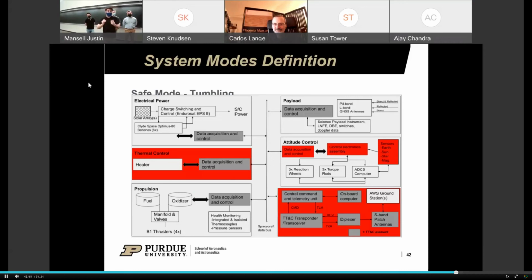We did look at the Simulink model, which allows you to input an initial angular velocity rate, a vector of initial angular velocity rates. We set that to 0, assuming that the deployment from the launch vehicle would be stationary, and then you would have to spin up into a nadir pointing rotation. That's where our 1.1 millinewton meter torque comes from, that initial spin up. It's pretty low, with very minimal momentum gain after that.